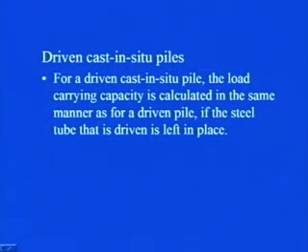Now, let us try to see driven cast in situ piles. First, we saw how driven piles work, or how we can find out their load capacity under compression. Then we saw bored cast in situ piles. Now, the third one is driven cast in situ piles. For driven cast in situ piles, the load carrying capacity is calculated in the same manner as for driven piles if the steel tube that is driven is left in place, that is in case of the cased piles.